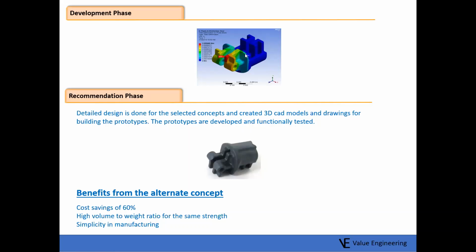We did the FEA analysis and saw the forces acting on the component and its yield strength. Compared to that, we are 2 to 3 times safer than the induced stresses in the component. So we thought it is safe to go with the PEEK plastic material.